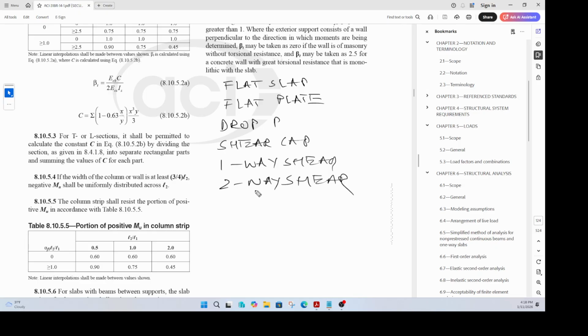We talked about how you can calculate the small vc value, which is the shear strength value. We talked about how you calculate your alpha, that defines the character of your beam, EcbIb by EcsIs, Is is slab, Ib is moment of inertia of the beam. And we talked about how you can evaluate the minimum thicknesses for slabs, and we also talked about the influence area, about the shear.